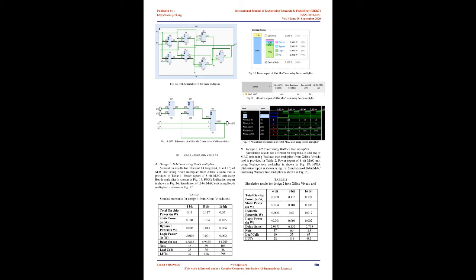The accumulator used in this paper is a parallel in parallel out shift register. It is the simplest of all the 4 configurations of shift registers. Both data loading and data retrieval occur in parallel in a single clock pulse. Hence it serves as the ideal choice for an accumulator. The block diagram of a 4-bit PIPO shift register implemented using D flip-flops is shown in Fig 3.